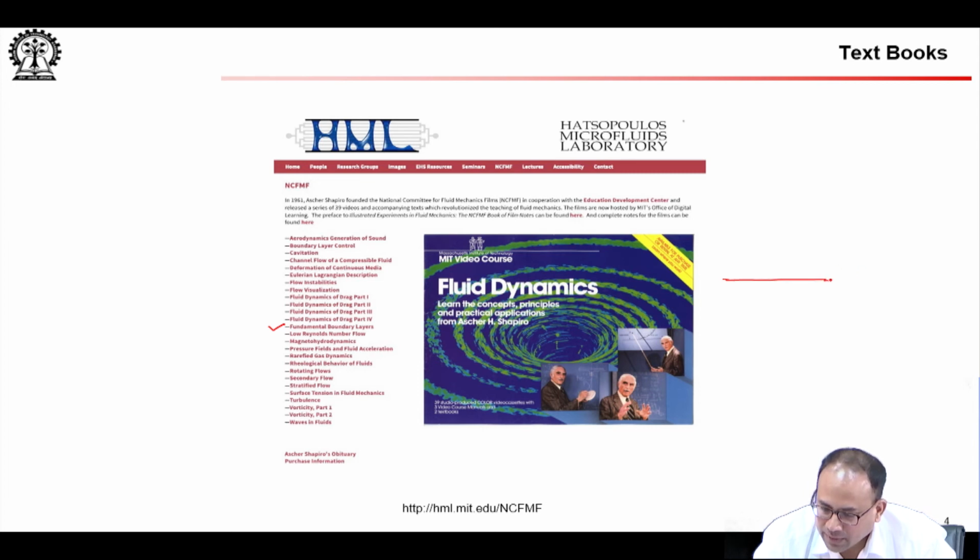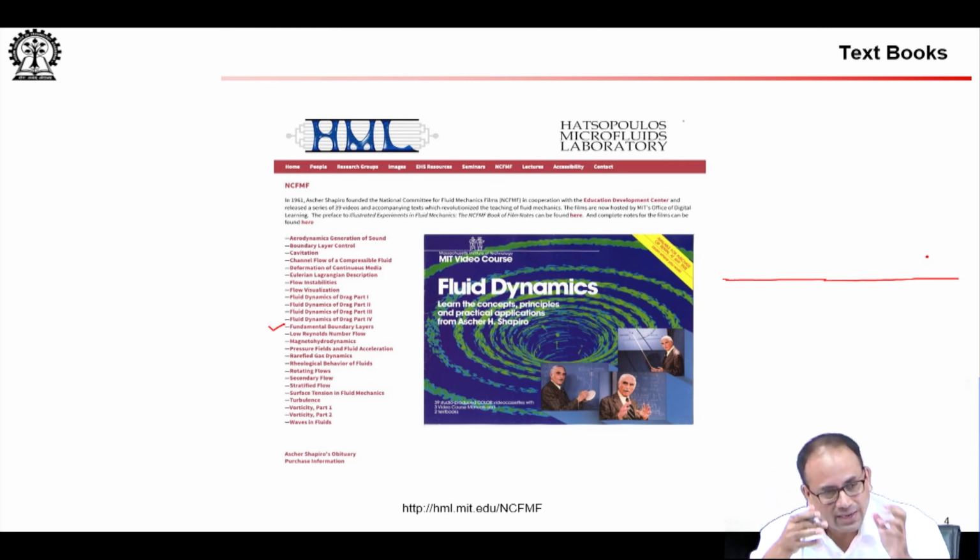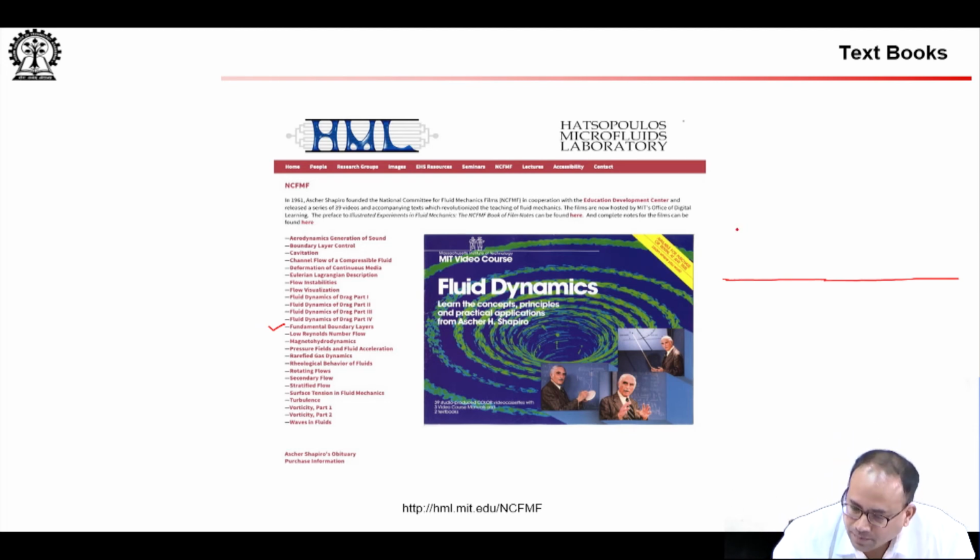And just like Mach number, remember, gives you the range of where compressible flow occurs, where supersonic flow occurs, where hypersonic flow occurs, where transonic behavior occurs. So, Mach number gives you an indication of all those behaviors. Knudsen number gives you where you should use free molecular flow as your governing equation for fluid behavior, where you can use Navier-Stokes with slip conditions. Navier-Stokes is essentially the governing equation for viscous fluid flow.